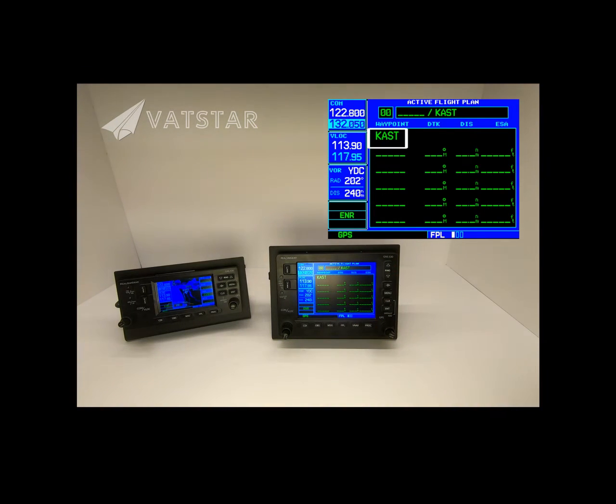Now often it's going to put the first waypoint as the closest airport that you're in, or the airport that you are on, right? In our case, like I said, we're in Kilo Alpha Sierra Tango. Something I want to make sure you guys are familiar with is that if you are on an airport that is not recognized on the simulator, on the GPS, you might get the closest airport to you. That is perfectly fine as long as you're aware of that. So make sure you check that before you go out flying.